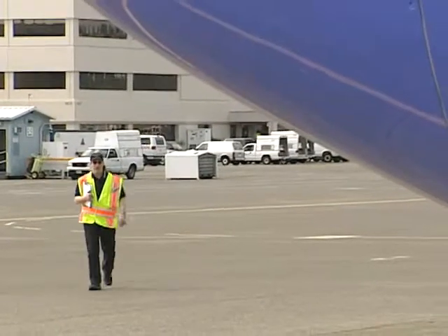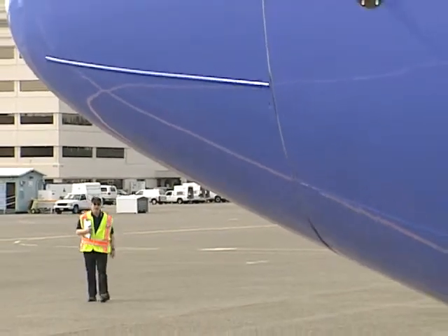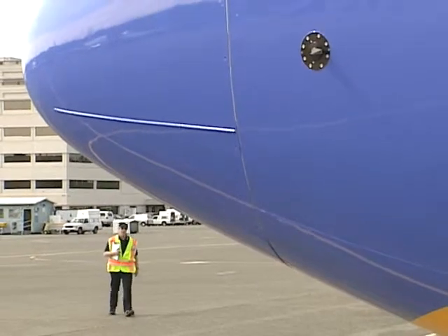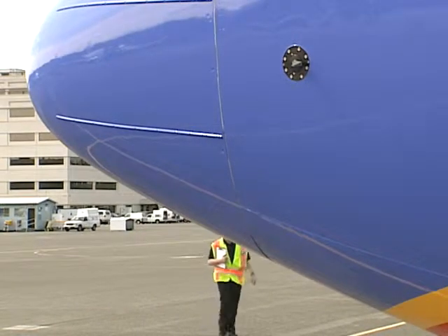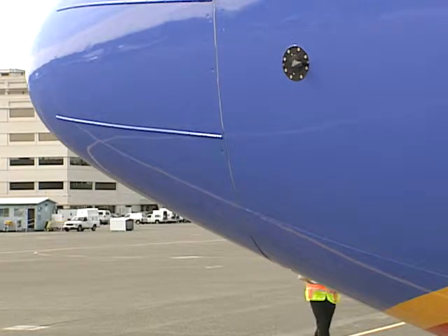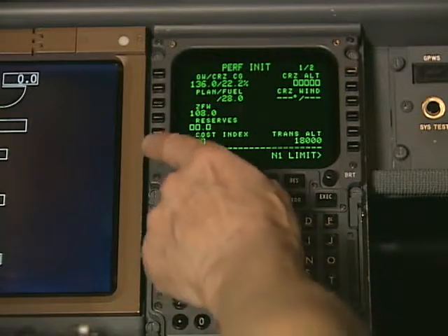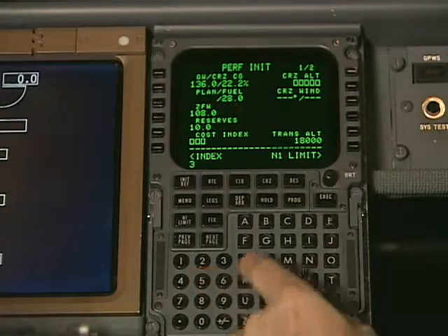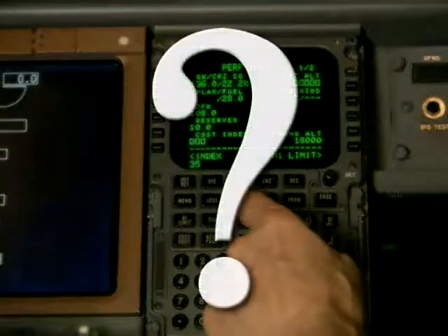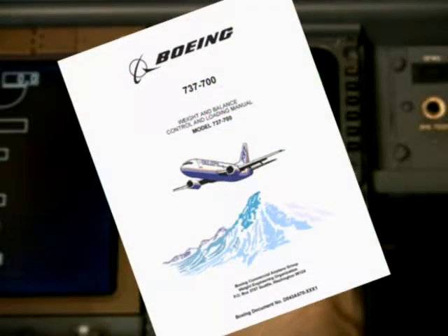Next, we need to conduct an airplane inventory. Experience has shown us that problems with getting an accurate basic empty weight often come from errors in this part of the process. So let's take a moment to understand why an accurate inventory is important. As mentioned earlier, in order to predict an airplane's actual weight during operation, you must start with the airplane's basic empty weight. But how do you know what is and what is not included in the BEW? That's where the inventory list comes in.